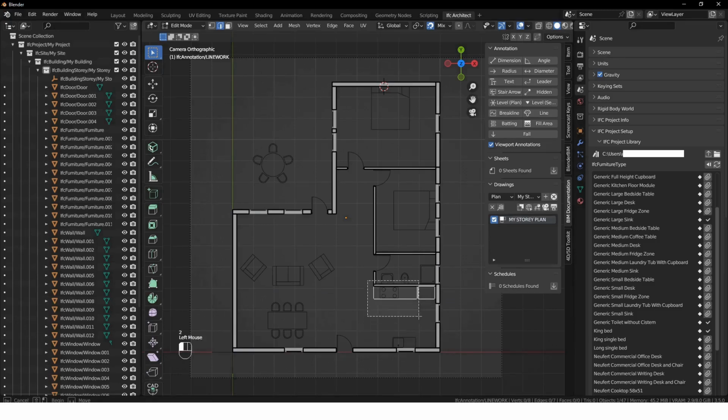Select 2, select just this one, or both of these. Shift D and then Y, bring down G Y so that it lines up there, and then select 2, select this one, G Y 1 to 100, press 1, bring it across, and there we've got a countertop.